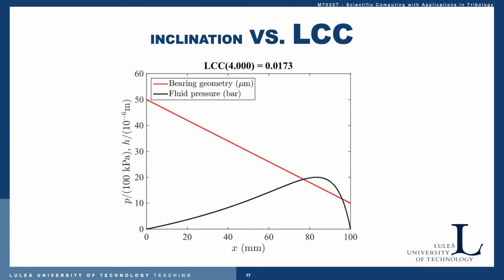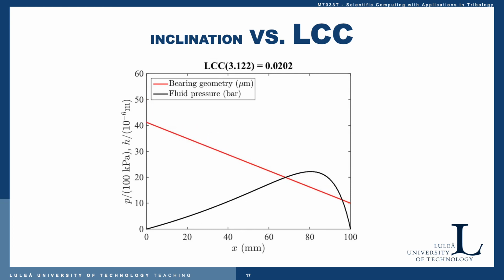So it's not favorable to have a larger inclination, and this is irrespectively of the speed and all other operating conditions of the bearing.